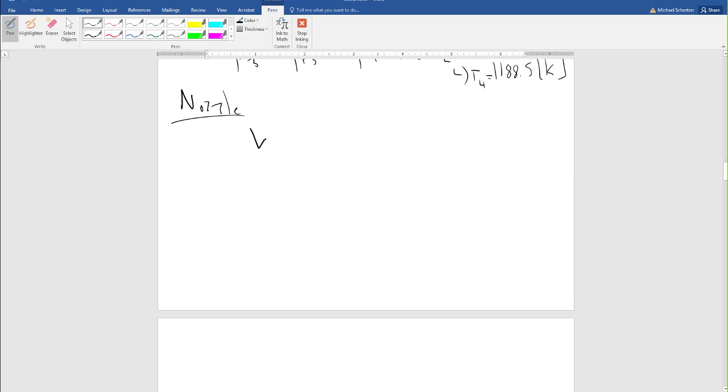This is the thing. Remember, the problem is asking for this. You're basically always going to have to find the outlet velocity on a turbojet. We know H4, but we don't yet know H5.